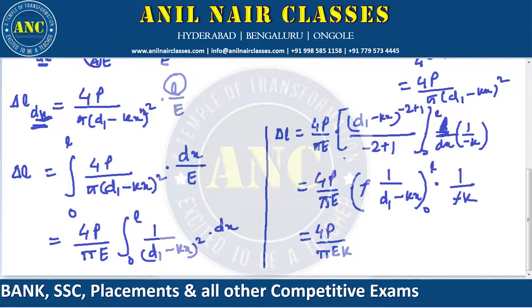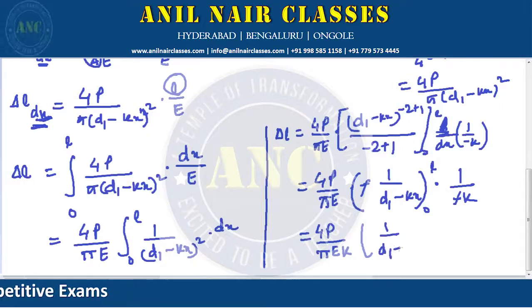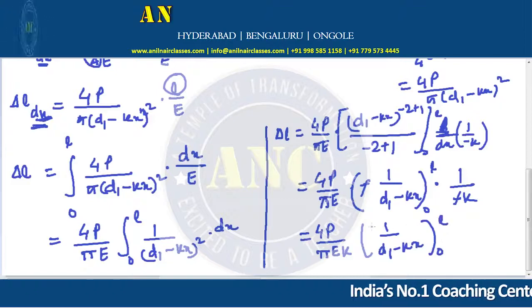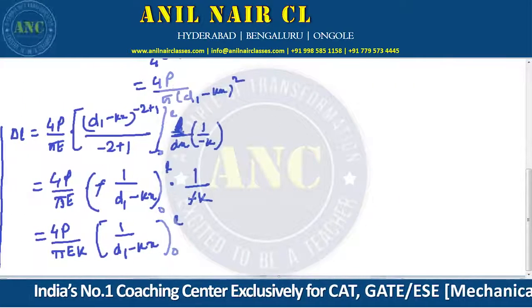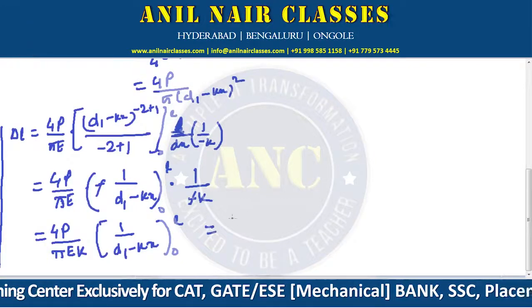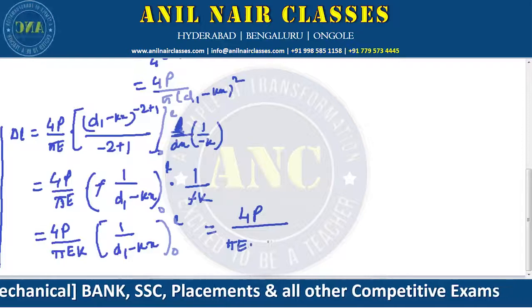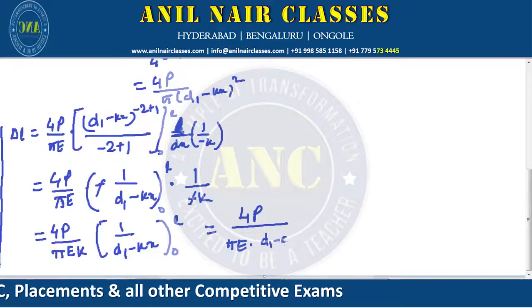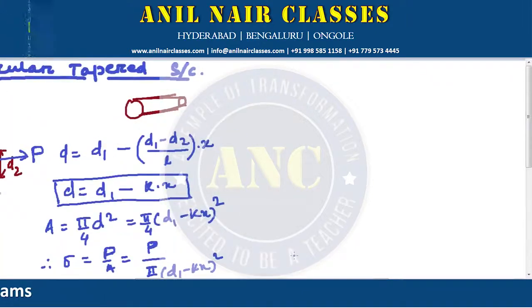This is from 0 to L, right? So 1 by (d1 minus kx) from 0 to L. When we solve further, this will be 4P by pi E, where k is d1 minus d2 by L, correct? See from here, what is the k value?